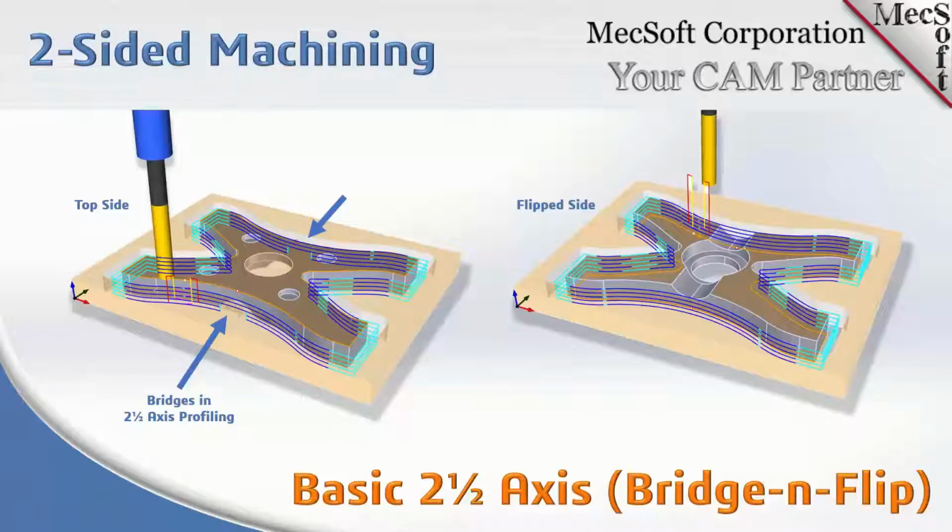Then after you're done cutting the first side, you'll take the stock off the table, flip the stock over. I have it flipped over along the x-axis, and add your work 0. You'll notice here the work 0 is in the same location, bottom left corner. That's important.